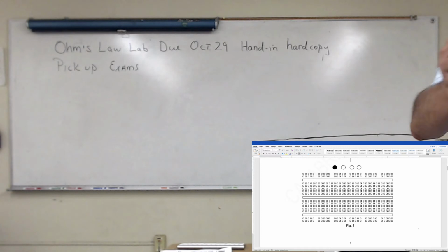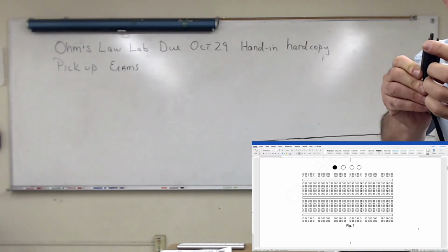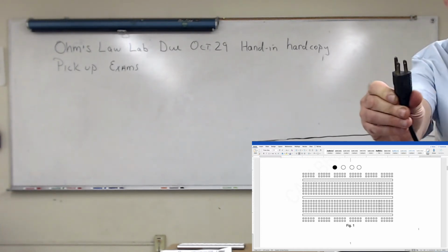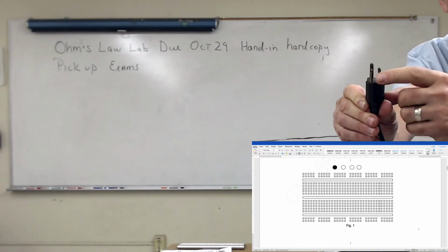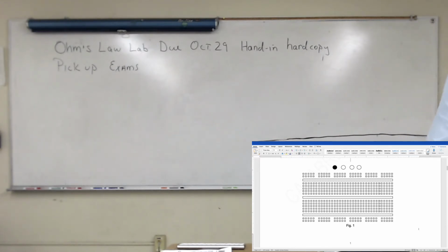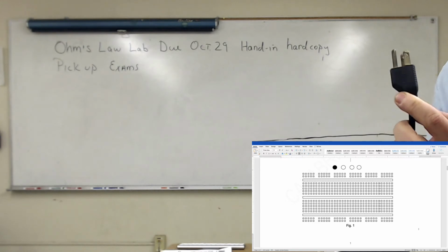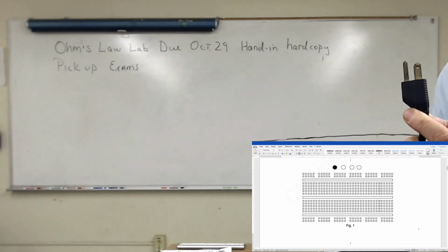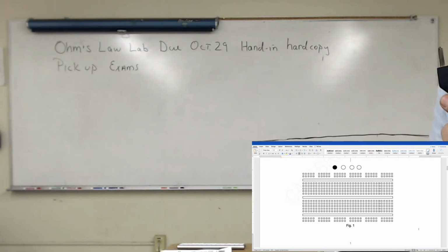If the resistance between these two wires, because they're connected to different wires, is 0, something is shorted, something's wrong. Okay? Or any two pairs. Any two pairs on here, as long as it's 0, there's probably something wrong. Okay? Unless it's designed so that they're connected. Okay. So you can use resistance to diagnose things.